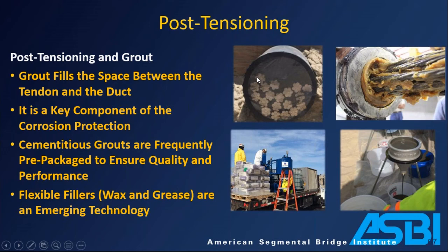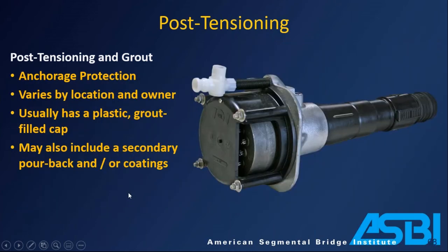Been an evolution over the years from sort of quick and dirty cement grouts to prepackaged grouts, and even an evolution in some places, again, Florida leading the way, of using wax and grease. The idea being that the protection of these tendons is really quite critical to the longevity and the serviceability of these bridges. So it is very important to do a good job. It's important to pay attention to what you're doing and make sure that you do a good job. The last thing about grout, they're part of the anchorage protection too. That's certainly a place that needs corrosion protection.